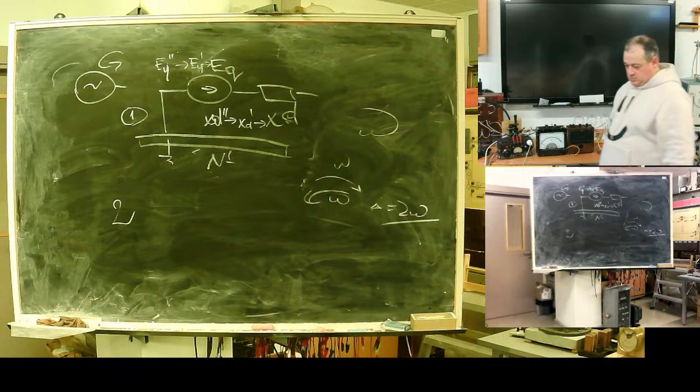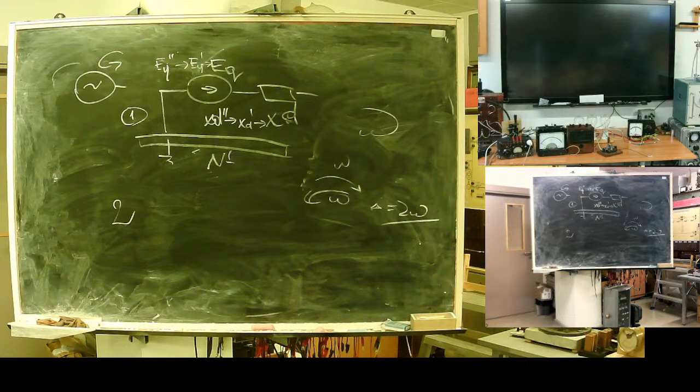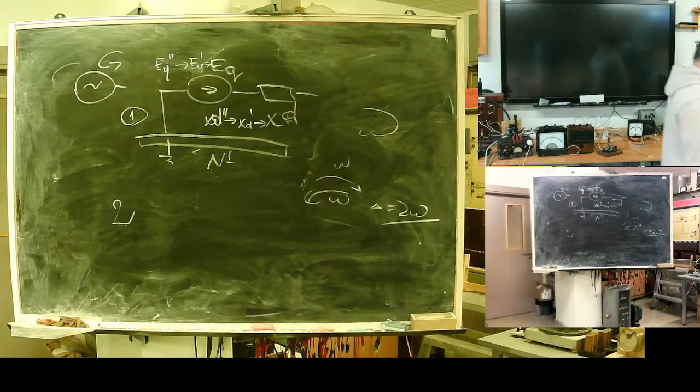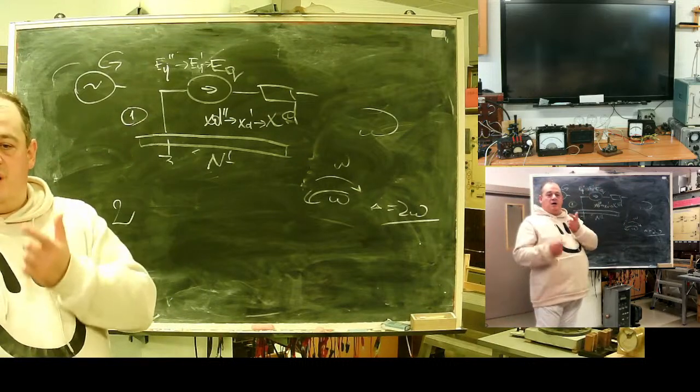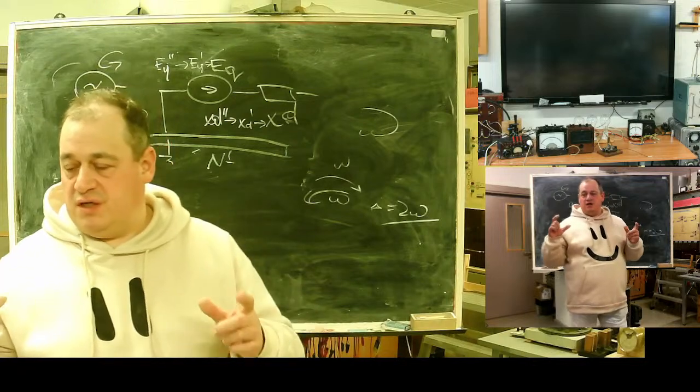For steam generators, for generators without damping winding, negative sequence poses a very high degree of danger, because the rotor shaft will overheat.